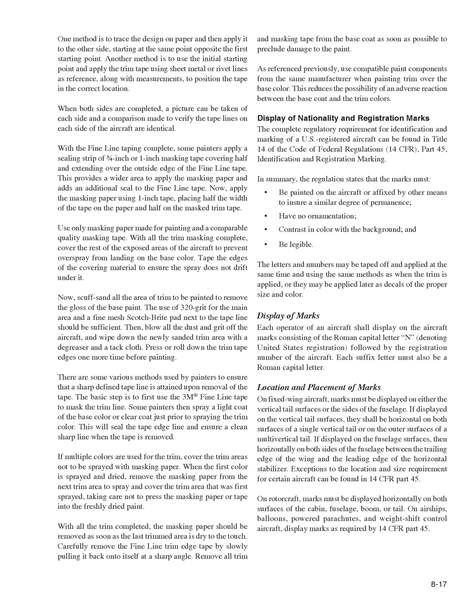Display of nationality and registration marks. The complete regulatory requirement for identification and marking of a U.S. registered aircraft can be found in Title 14 of the Code of Federal Regulations, 14 CFR, Part 45, Identification and Registration Marking. In summary, the regulation states that the marks must be painted on the aircraft or affixed by other means to ensure a similar degree of permanence, have no ornamentation, contrast in color with the background, and be legible.